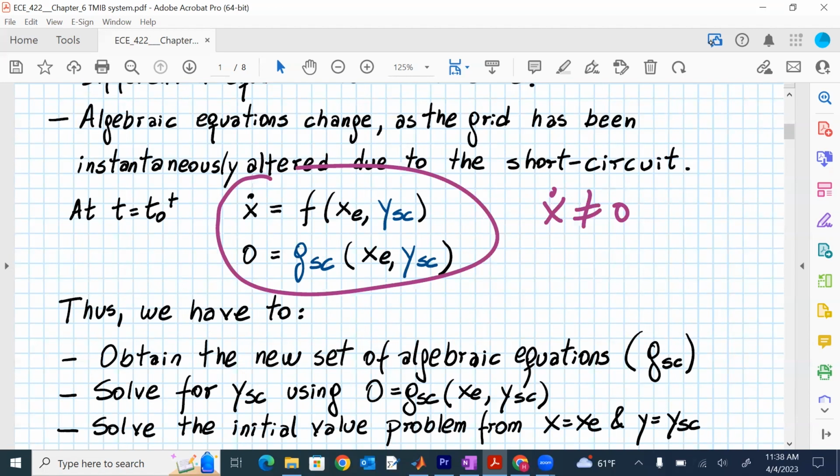When we have a disturbance, now a short circuit in this case, that will create a fundamentally important change in the grid. We're considering a three-phase short circuit. And for this problem, we're considering that the short circuit occurs at bus 2. So the voltage at bus 2 all of a sudden is sent to 0. To consider that in our grid representation, the algebraic equations that we have need to be modified to consider the current condition for a short circuit at bus 2.